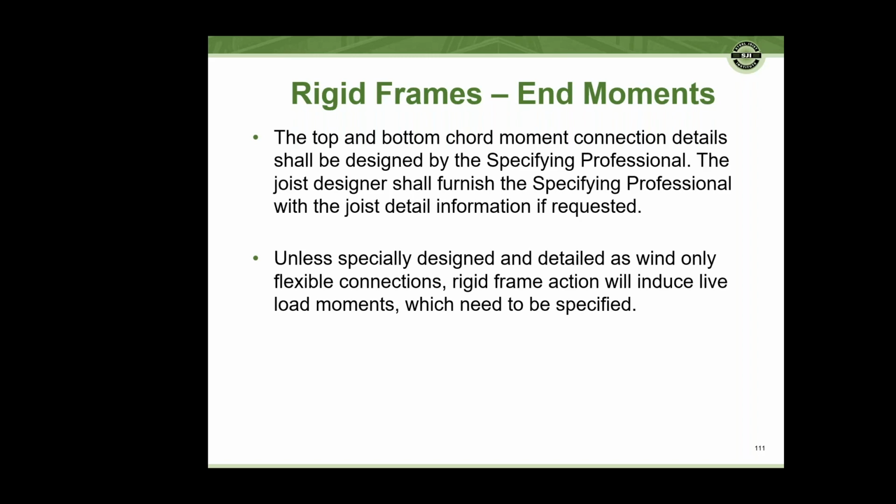Rigid frame action will induce a live load moment, which needs to be specified. So you have that live load moment now that you've got that fixed end condition on a joist or girder, and it needs to be considered.